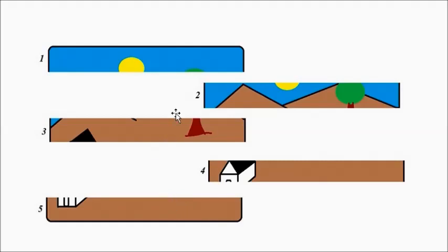The odd field contains odd number of scanning lines, the even field consists of even number of scanning lines. So in case there is any mismatch in the rate at which the scanning takes place for the odd lines and the even lines, the equalizing pulses are used, so that both scanning takes place in step with each other, in sync with each other.